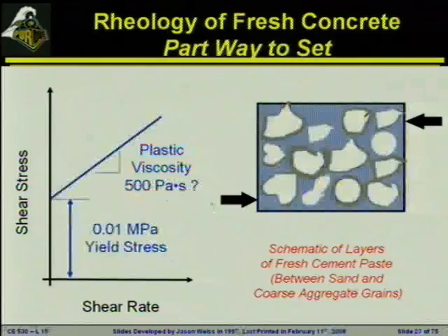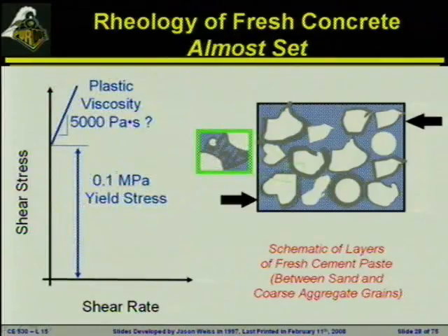Well, as the system begins to hydrate, those particles start to grow. They start to get bigger. We have chemical shrinkage that reduces the overall volume. We start to get things starting to develop inside of the pore solution, and we notice that that yield stress is going to start to rise. And it's going to continue to rise, and where we're going to start to see this huge jump take place is all of a sudden once these particles start interacting with water and start banging into one another. And that's where we're going to start to see the shear stress go way up.